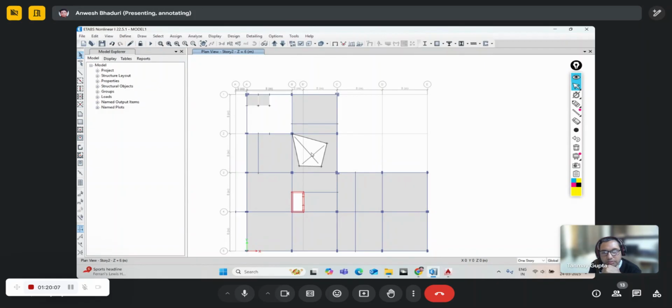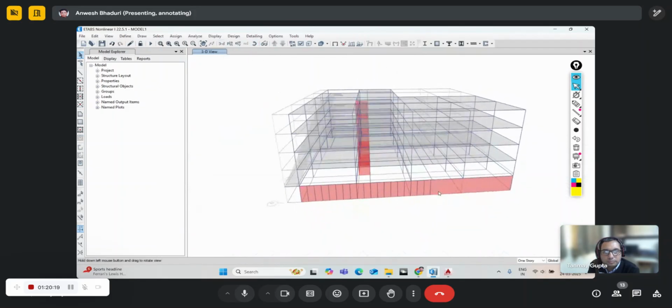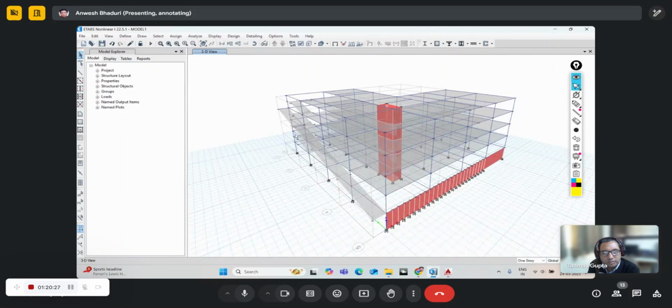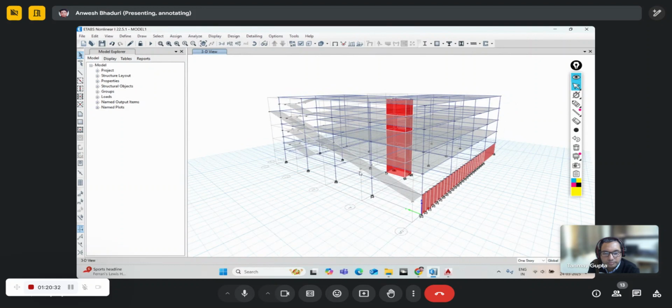We don't have to discretize for this case. Yes, for wall elements, we need to do that. I think I have covered these topics in detail now. Your inclined wall will be similar to your drawing of a ramp. You just need to have that inclination over there and place the walls as per the slope, using this polygon shape slab element over here.